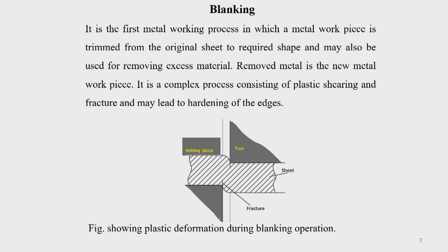Blanking is the first sheet metal working process, because if you are getting the material in a coiled form, as per your requirement you have to cut it to size. For that, the blanking operation is done. There is only a small difference between shearing and piercing. Blanking is the case where, after cutting, whatever has been removed from the basic form or from the sheet is what you are going to use. Then you call it blanking. It is only a terminology difference.